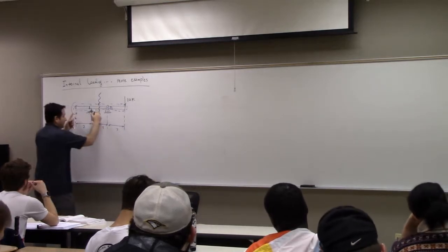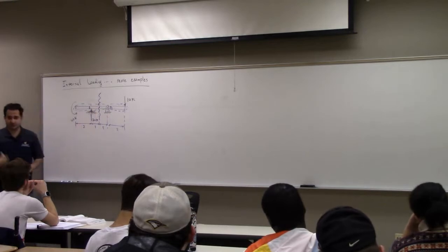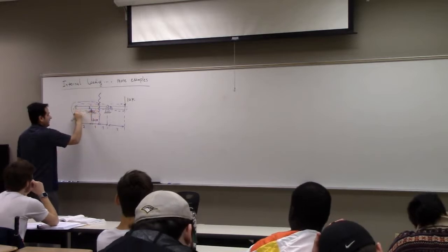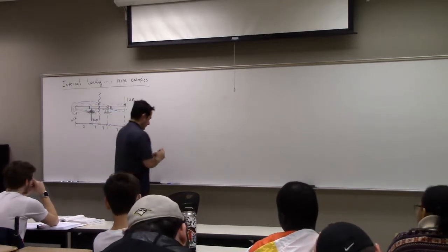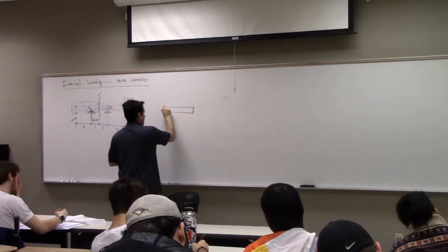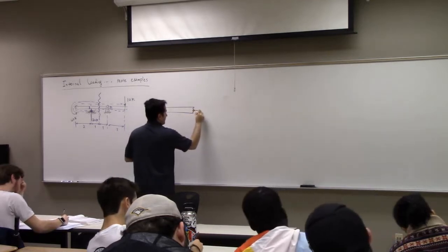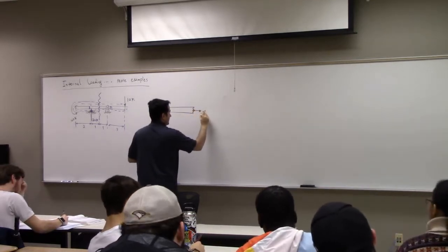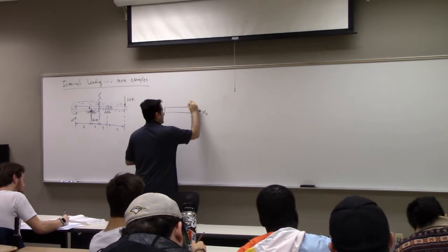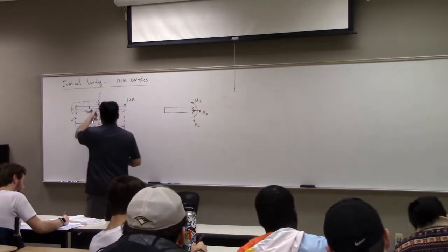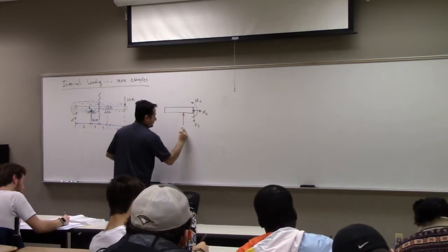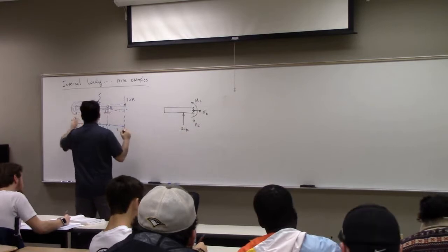Now I do my main job. My goal was to find the internal loading at point C, which is 3 components at most. Then I take this system right now, and I draw the FBD. So if I do that, I get, let's call this N, axial load at C, VC, MC. You have 3 components at point C. Then if you walk, you come to this 20K, which I just found, and 60K.